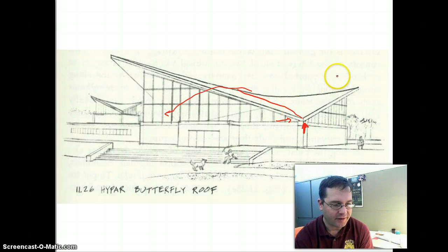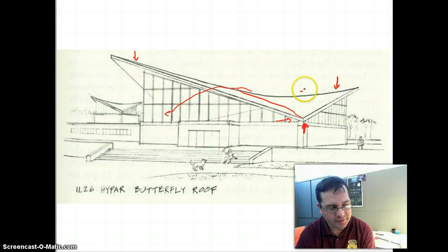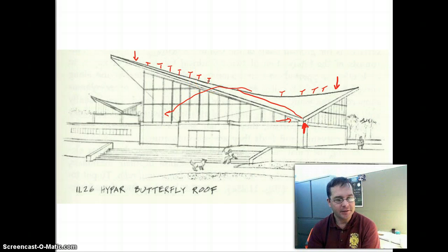The other thing is that when the weight is placed out near these other kind of apexes of this, tension develops along this top chord of this concrete casting here. And so that's typically handled either post-tension with tendons, or could be handled with reinforcing bar. But once those concerns are taken care of, this is a very strong roof.